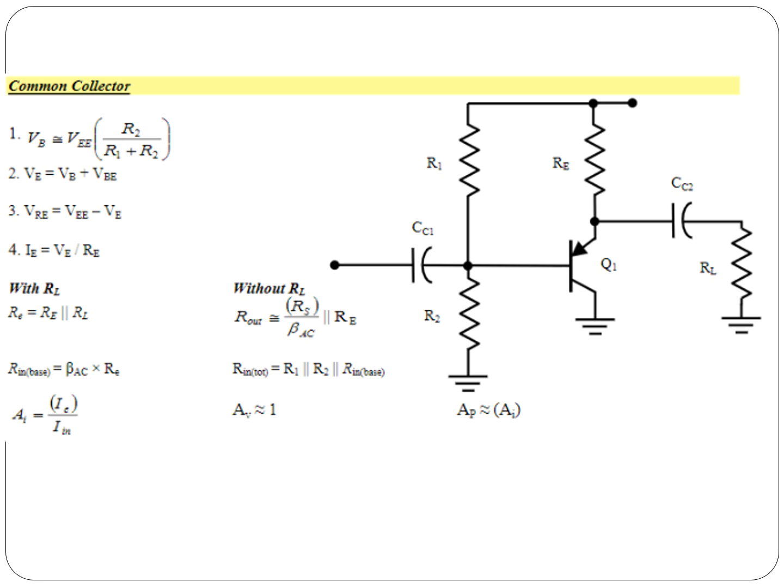Current gain. So we're going to look at current gain being equal to I sub E over Iin. Remember that we have a voltage gain of 1. And so overall, what this slide means is you're going to have a high current gain, unity voltage gain, excellent buffering, easy to bias and analyze, and this is your common collector amplifier. It's a voltage follower that quietly empowers your signal chain without distorting it or dragging it down.